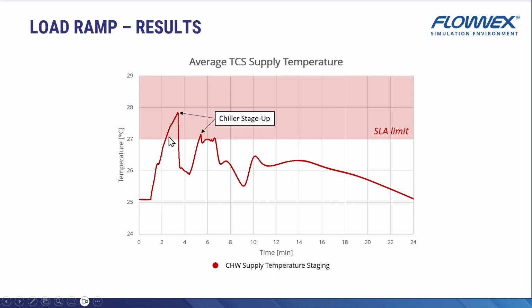To eliminate this problem, the chillers must be staged up before the active buffer tanks are depleted. One way to ensure that this happens is to monitor the IT load directly and base the chiller stage up control logic on this. The second scenario is set up to do this.